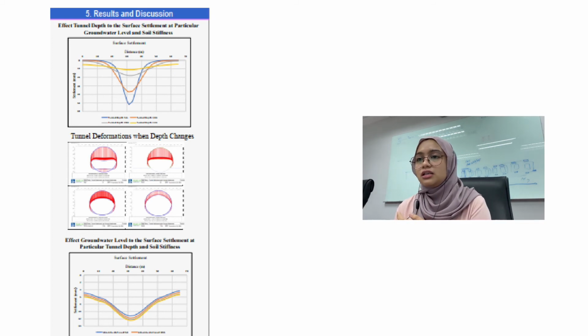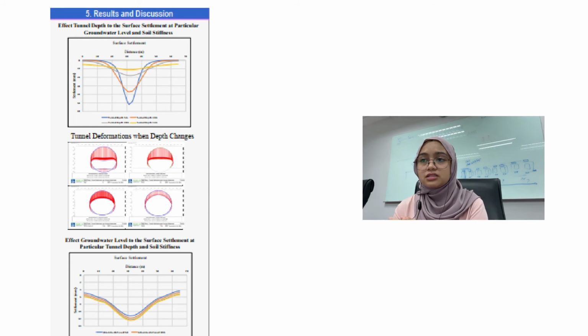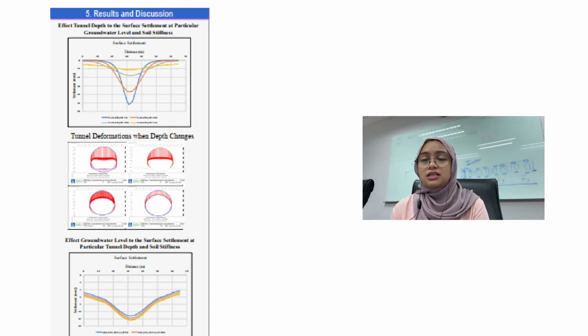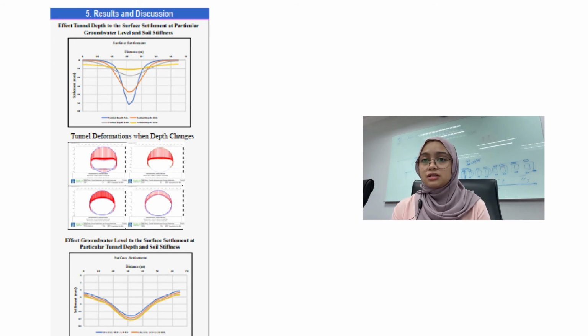The MRT design criteria state that the accepted tunnel lining deflection under load combination must not exceed 25 millimeter on radius. However, this study does not represent the actual case on site, because there are a lot of considerations that need to be considered but not implemented in this research.